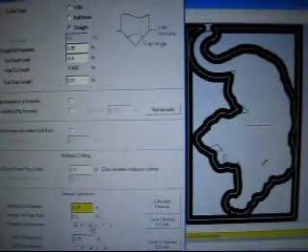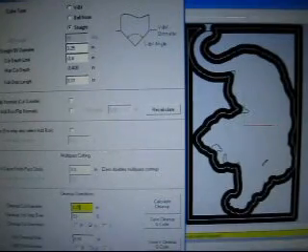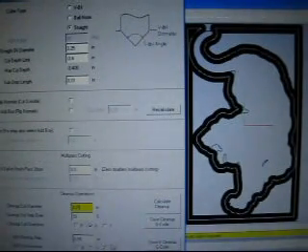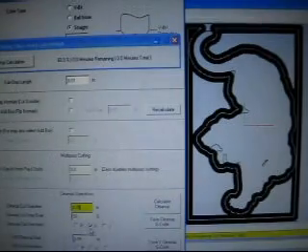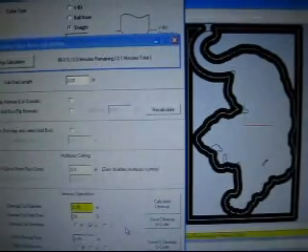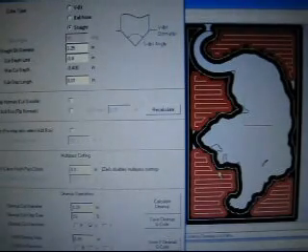Okay, and what we want to do is cut only in the X direction. This bottom one we don't need. That's for V-bit cleanups. This is for cutter diameter cleanup. So I'll calculate the cleanup in only the X direction right now. Okay, so that's not what we want.